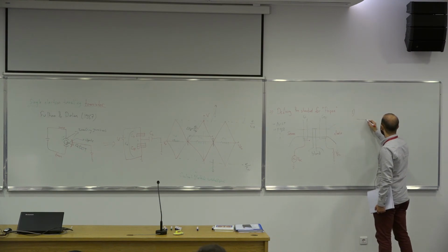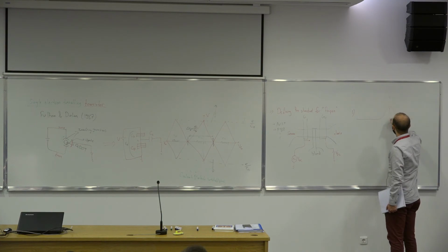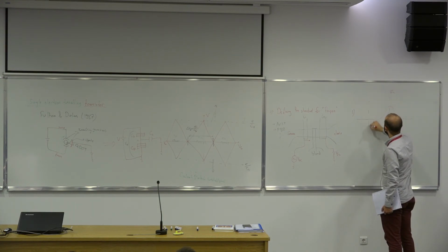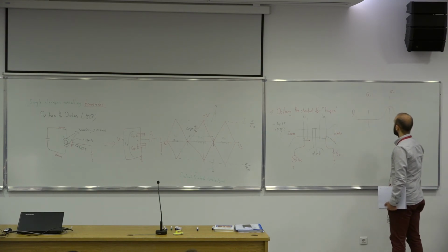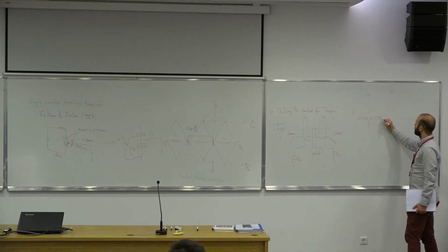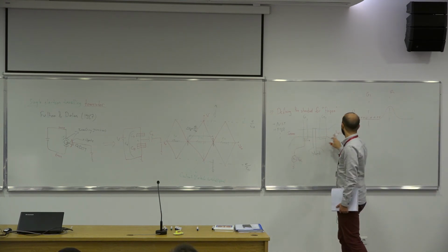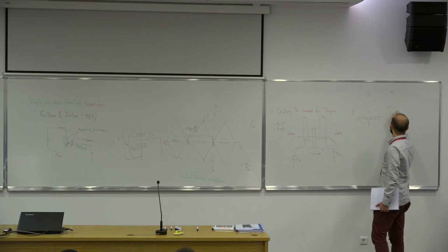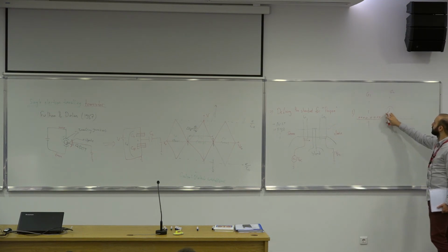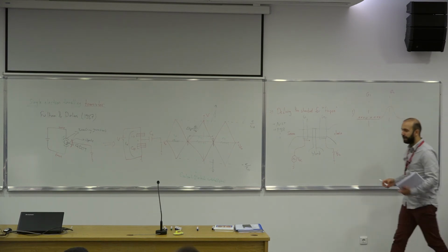So let me draw the potential landscape. So this is G1, G2 region. This is gate 1 region. What happens is that, let's say these are my electrons. Electrons will reach till this point. So you set the bias between the source and drain in such a way that electrons cannot tunnel or go through this potential that's created by gate 2. And then